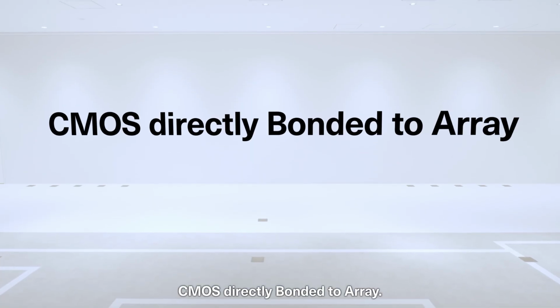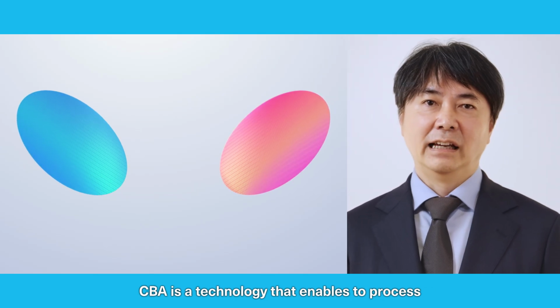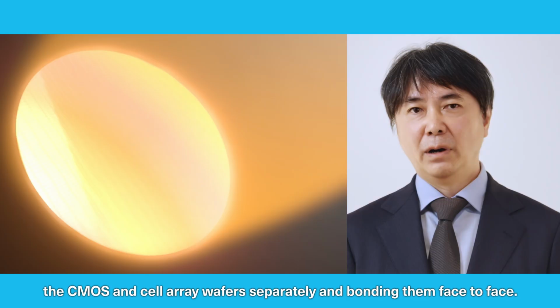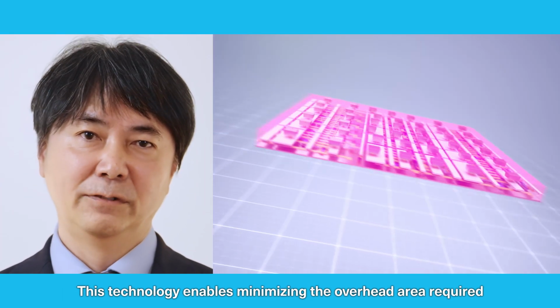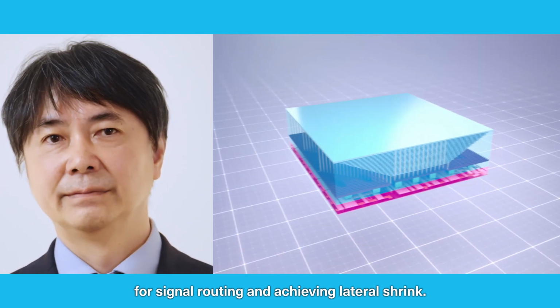CBA is a technology that enables us to process the CMOS and cell array wafers separately and bond them face-to-face. This technology enables minimizing the overhead area required for signal routing, achieving lateral shrink.